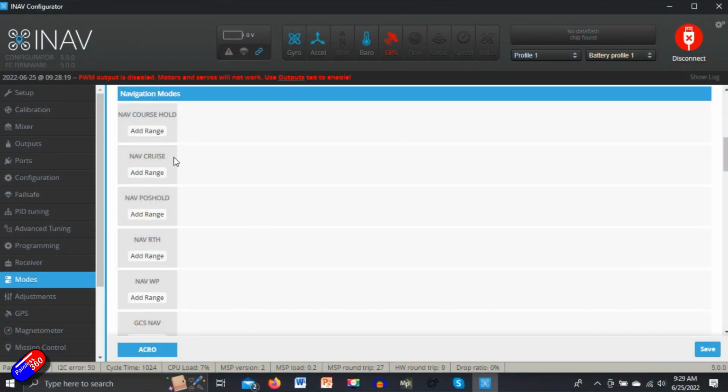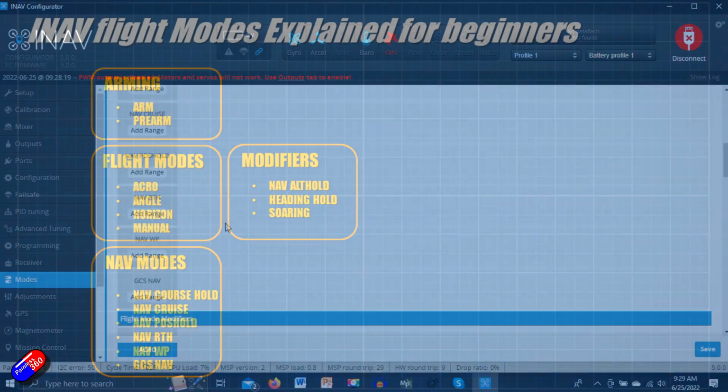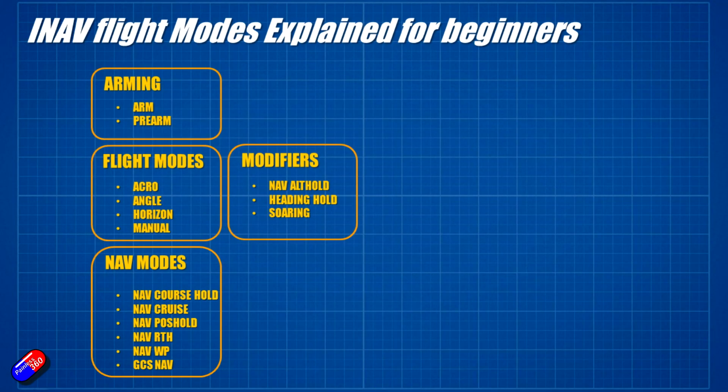And the pilot changes direction via the roll or the yaw stick on the radio. Yaw is usually smoother, and INAV will manage the throttle. So you set your cruise throttle in INAV and it'll basically run at that, but it won't manage the height. So it relies on you having set the attitude of the craft up perfectly. So at cruise throttle, it's going to just fly along. This one is just basically keeping your model on the same course.